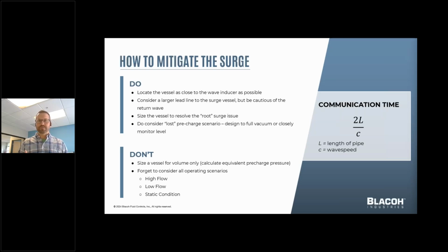Now, communication time is basically how long does it take for the wave to travel from its point of origination or induction point all the way to a point where it can reflect and come back towards the source. This is a function of the length of the pipe and the speed of sound in that pipe. Very simple calculation, but the reason that we spend so much time talking about this in previous webinars is because it has a big impact on the magnitude of the water hammer event.